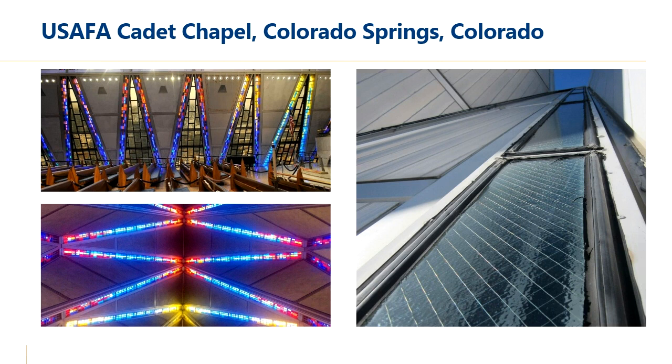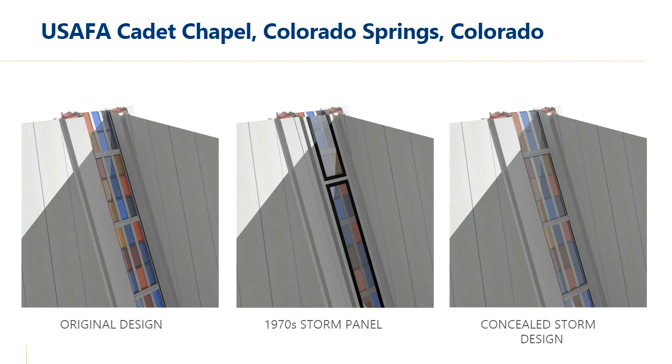But the cassettes can't really be preserved and made watertight. So to create a watertight building, we'll continue to use a storm window approach, but one that maintains as much of the original design intent as possible while providing a functional window system. One that preserves and reveals the historic dalle de verre cassettes. The solution incorporates a new line of glass nestled into the profile of the original enclosure scheme. We'll see how we did that in just a bit, but first let's look at the efforts to preserve and restore the dalle de verre glass and their cassette frames.